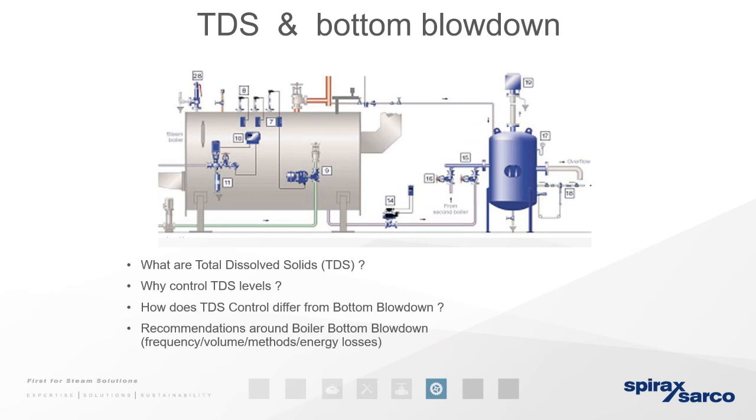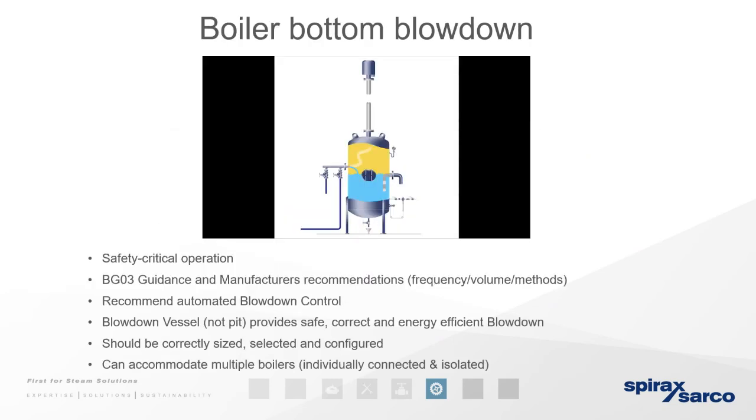We do this by opening a valve underneath the boiler, where the pressure inside the boiler will discharge this particulate to waste. We call this bottom blowdown, and this can be done once per day, either manually or by an automated timed process. Remember, this blowdown is pressurized hot water that will be at temperatures in excess of 100 degrees Celsius, so it needs to be able to vent away any flash steam to atmosphere and cool down, usually over a number of hours,